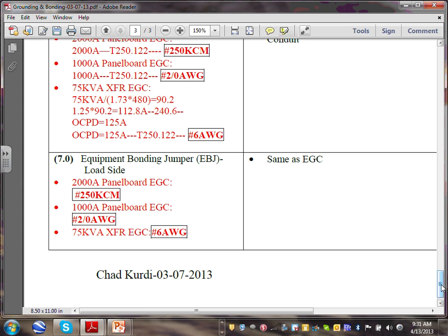So you take a 250 kcmil to the bonding bushings. Now what happened is I have 5 conduits. Do I have to bond? Remember, 5 conduits I have. So can I daisy chain them with the 250, or can I go from each one of them to the conduit with the 250? Either way.